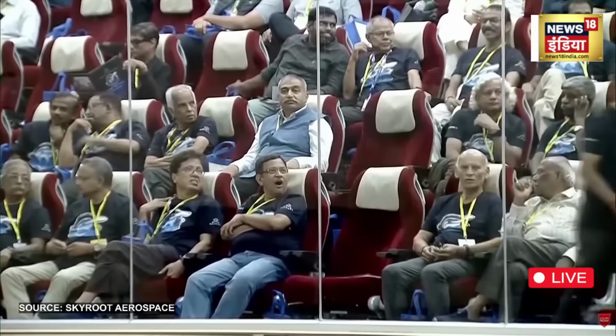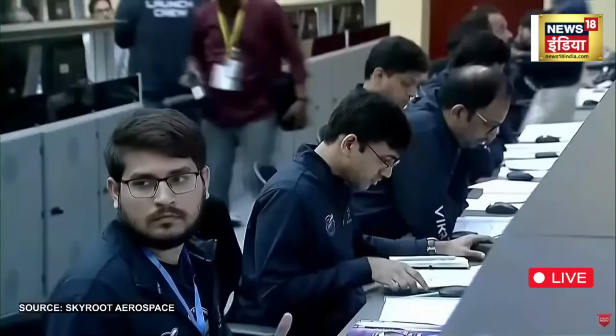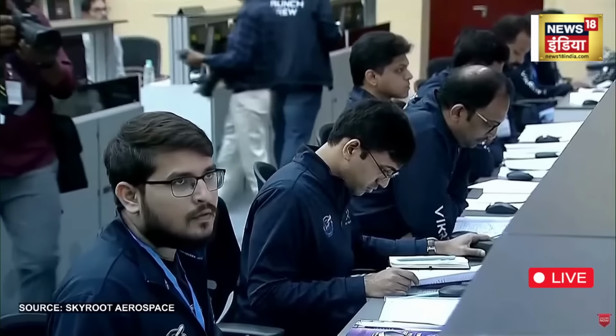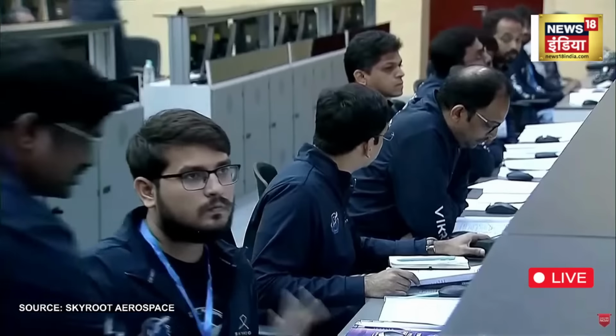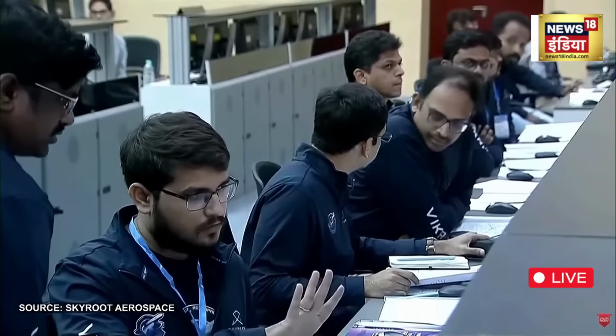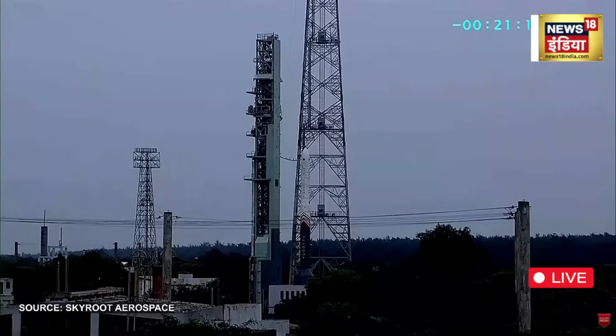That's really interesting to hear, Suresh. And coming back to steering of a rocket engine, for the information of all of our viewers, this is a rocket model that I'm holding in my hand. If you suspend it in the air or space, we can say it has unconstrained 6 degrees of freedom, out of which 3 are straight line motion, or let us say translational, in which it can move forward, backward, upward, downward and sideways, and 3 degrees of rotation are rotational, which we call pitch, yaw and roll.